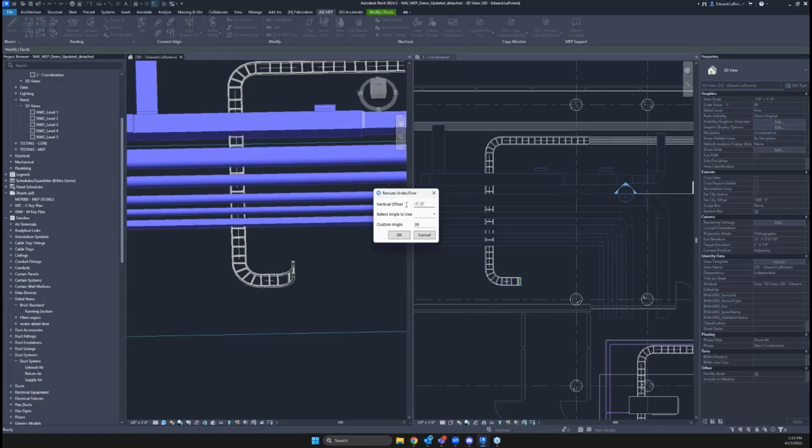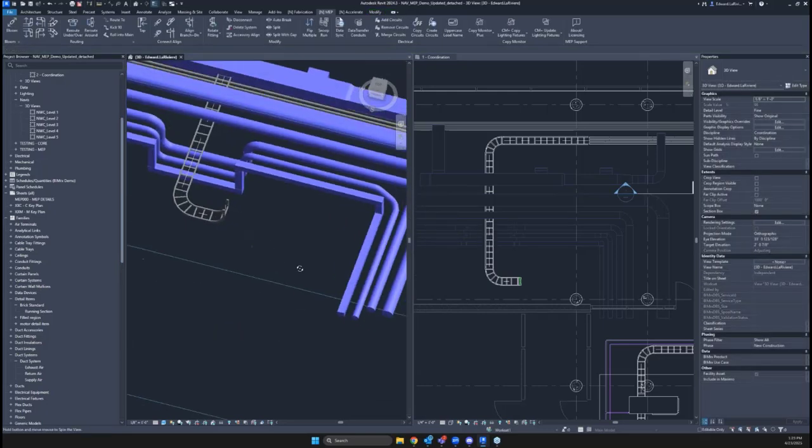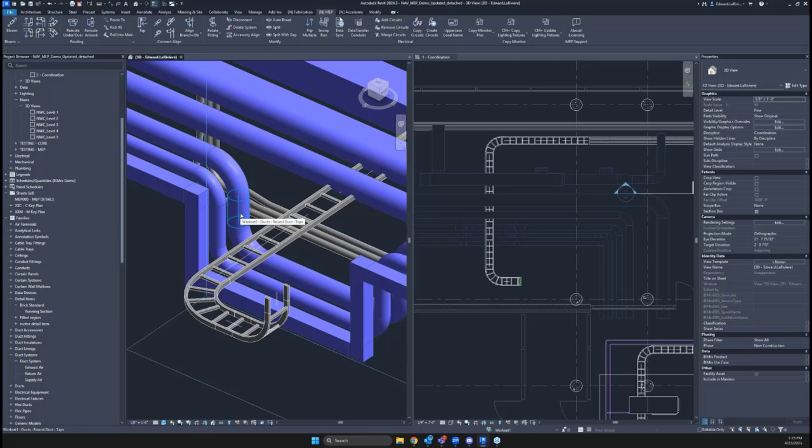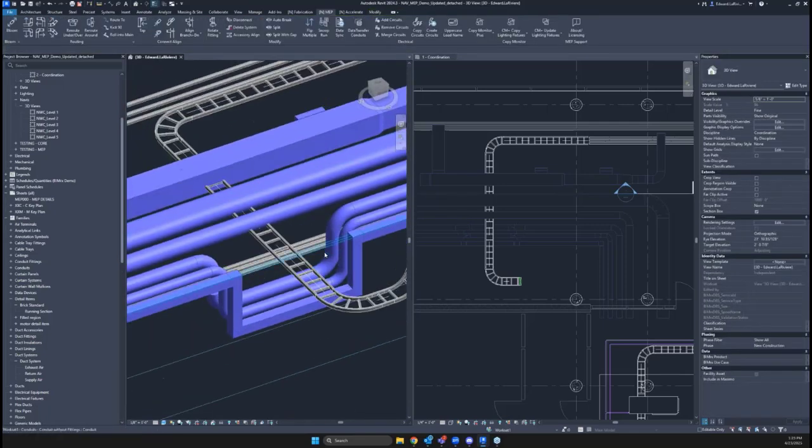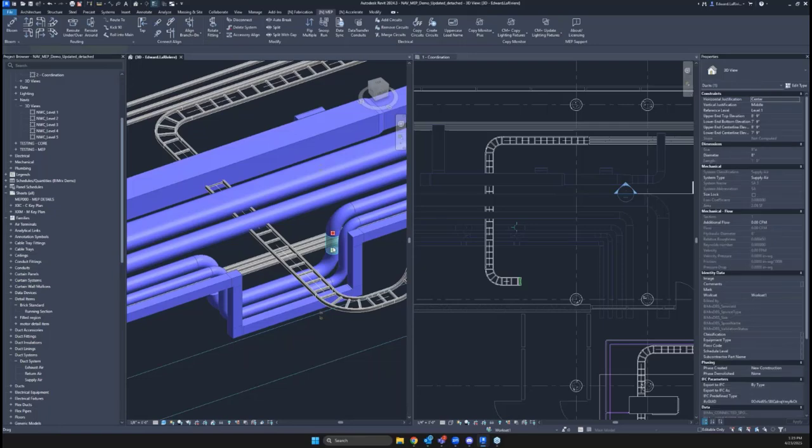I'm just going to highly recommend you do some really big numbers here, because ductwork fittings are huge. So do make sure you leave room for those fittings. Otherwise, we'll just pop a warning letting you know there's not enough space. Something really nice here as well is some fitting on fitting connections using that move connect tool.